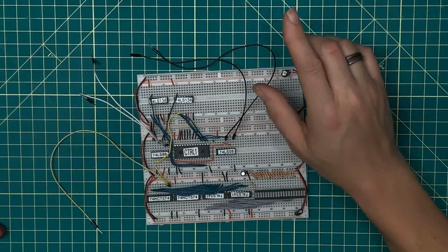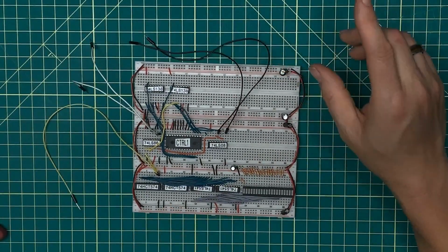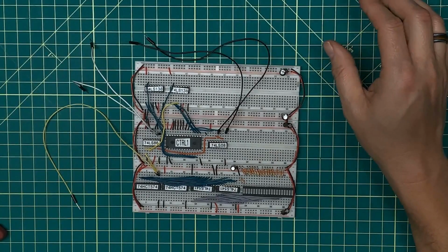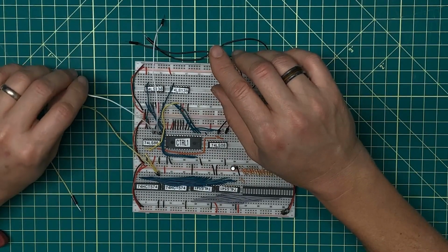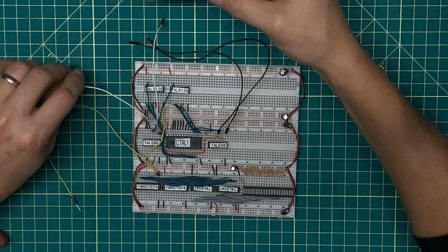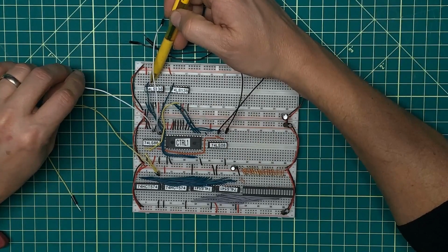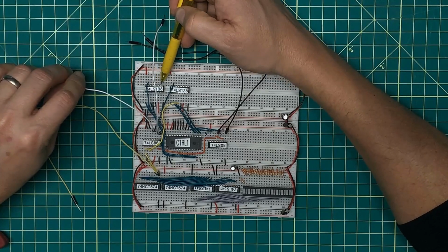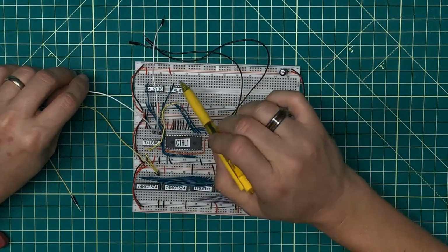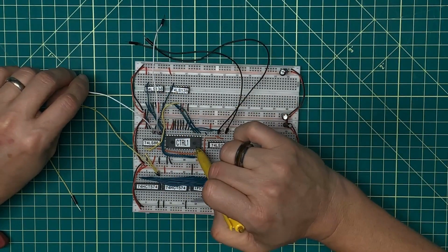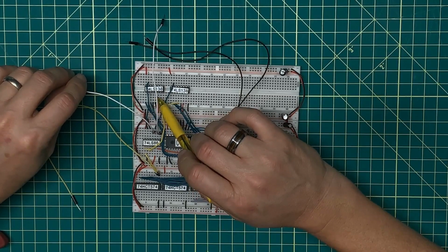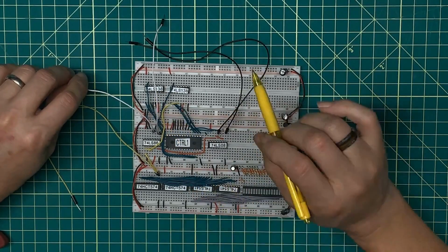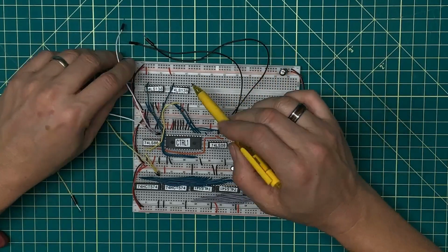So let me get these cleaned up a little bit. That then is the wire up for the control signals to control the program counter. Again, I have the assert to address bus 1 for the program counter. This would be some other register here. This would be a third register. This would be a fourth register, etc., all the way through. And the way I have this wired up, a value of 0 asserts the program counter out onto address bus 1. So that's very nice.